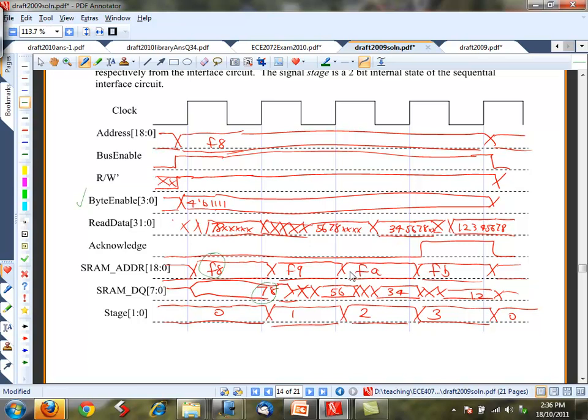I think the ordering, you have to worry about whether the least significant byte goes at the lower address or is it the other way around, big endian and little endian. So this is assuming a big endian protocol. So we read out the numbers and they get added to the appropriate place in the read data.